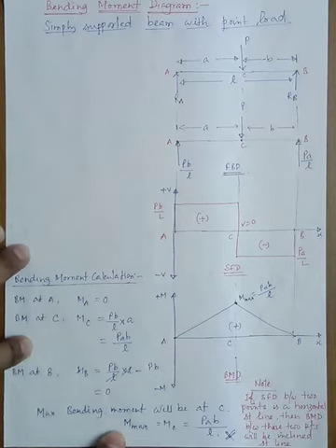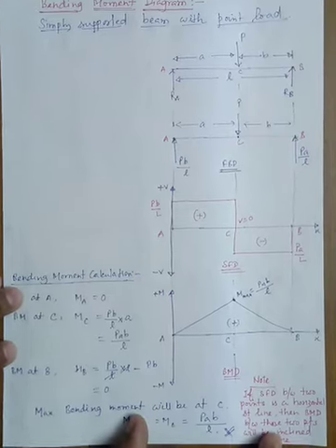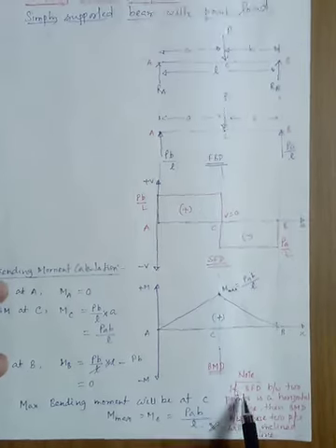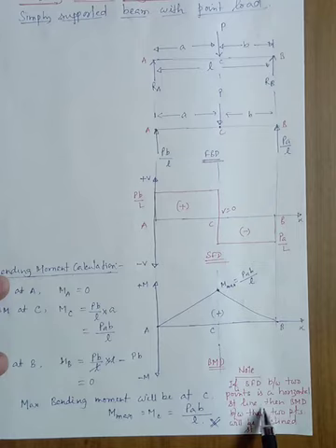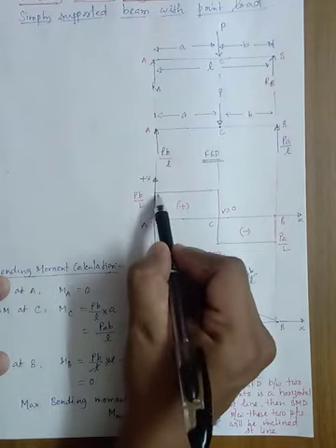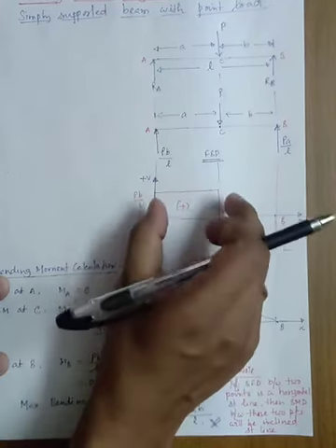And at point B it will be 0. Okay, so one important thing you need to note, it is written at the very corner, so I think you can see it. If the SFD between two points is a horizontal straight line, then the BMD between those two points will be an inclined straight line. So see the SFD between two point loads.